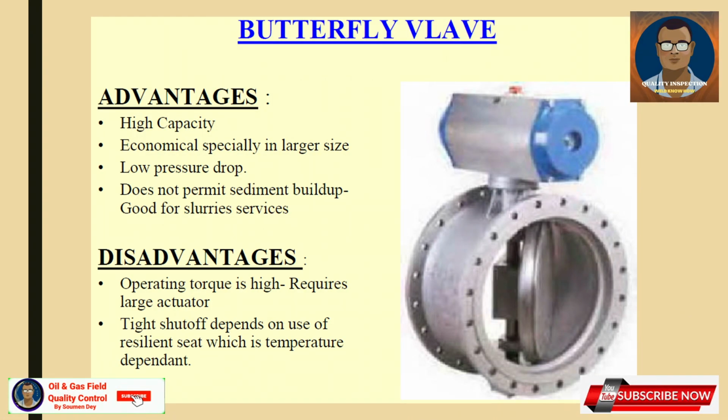Butterfly valve. Advantages: high capacity, economical especially in larger sizes, low pressure drop, does not permit sediment build-up, good for slurry services. Disadvantages: operating torque is high, requires larger actuator. Tight shutoff depends on the use of resilient seat, which is temperature dependent.